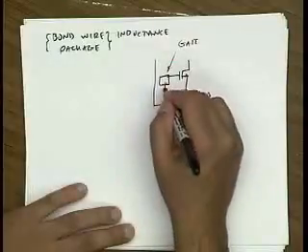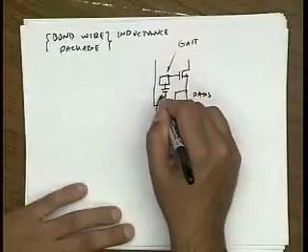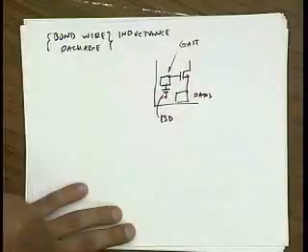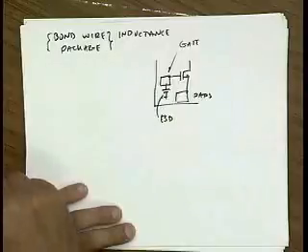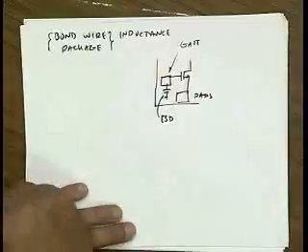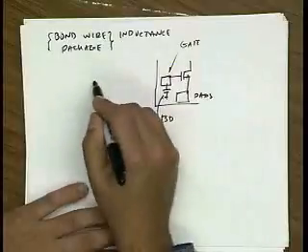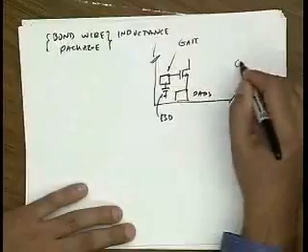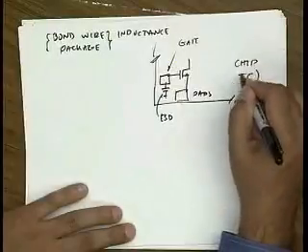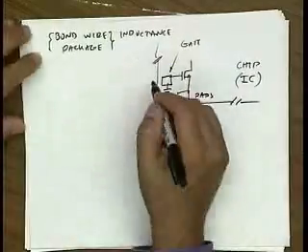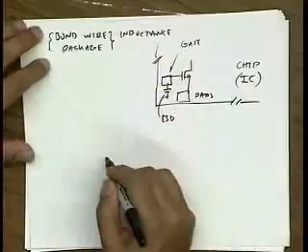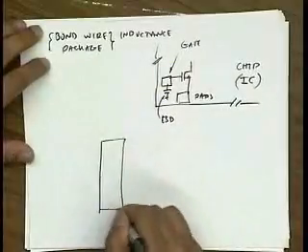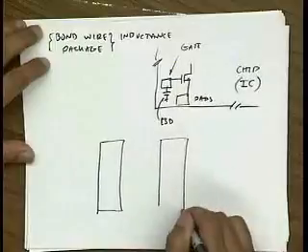So I have to put ESD, a device for electrostatic discharge. If there's any static buildup on this node, it clamps it to ground and prevents it from going into this device. Okay? And then I have to house this chip. So this is my chip. This is the IC, integrated circuit chip. I have to basically put this into a package, and even this is not to scale.